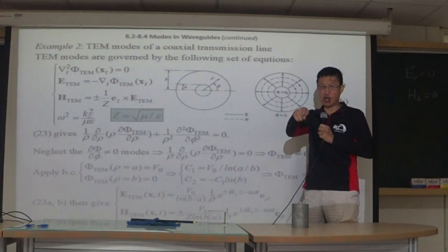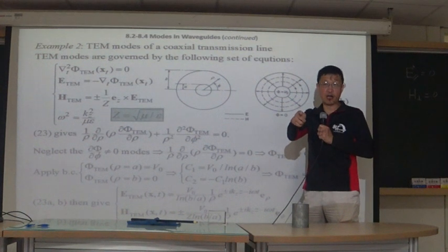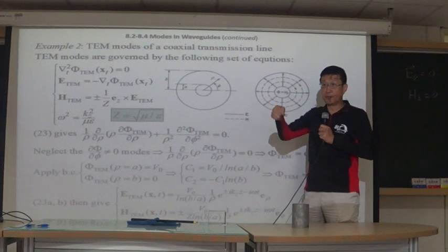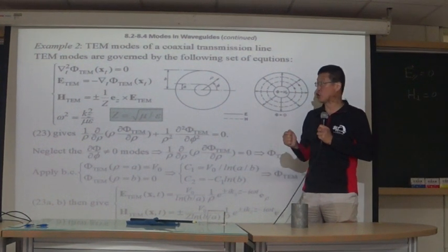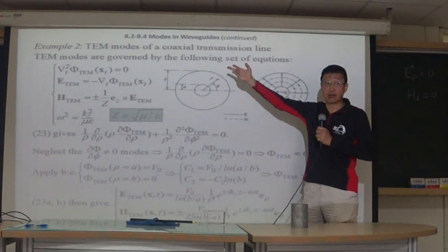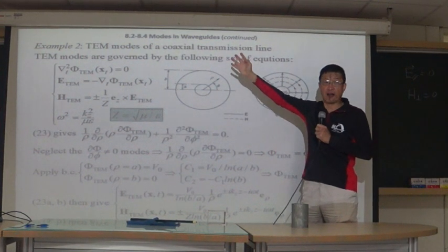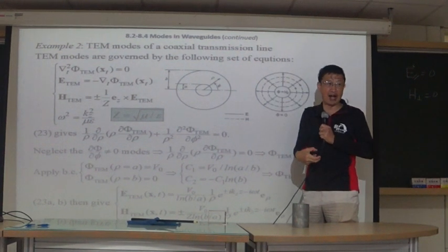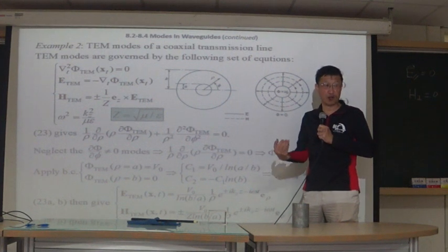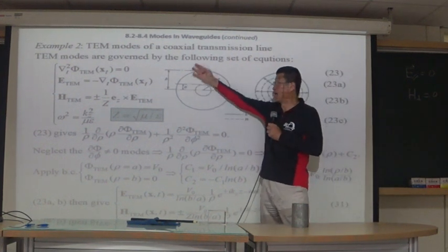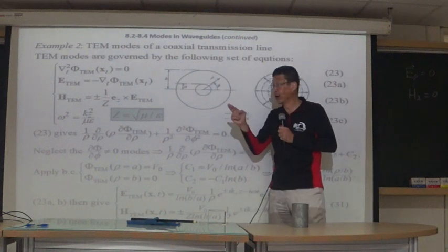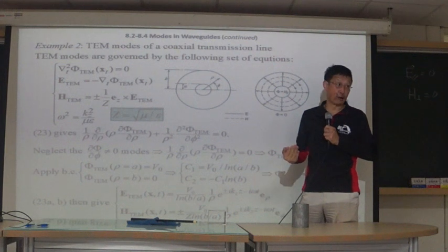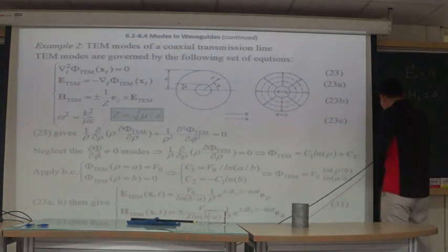If you check your cell phone or your notebook, you can see they use different structures. They use coaxial cable, yes, but not waveguide, because a rectangular waveguide is too bulky, too large, not good to use. So they use transmission lines like coaxial cable, and they use microstrip or strip line.